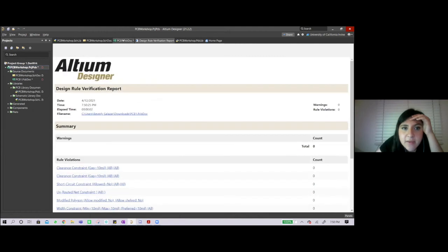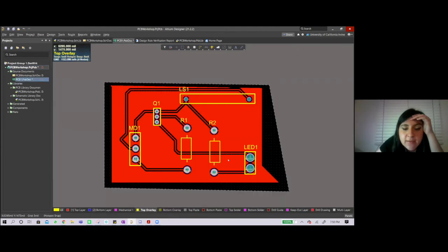These are basically used as a way to keep your IPC standards. So you could input the generic ones that you could find online, and you could stick to those, and then your system will be clear of any short circuits or antennas. But you could also bend the rules a little bit if you have systems such as this where it's not going to dissipate that much power.